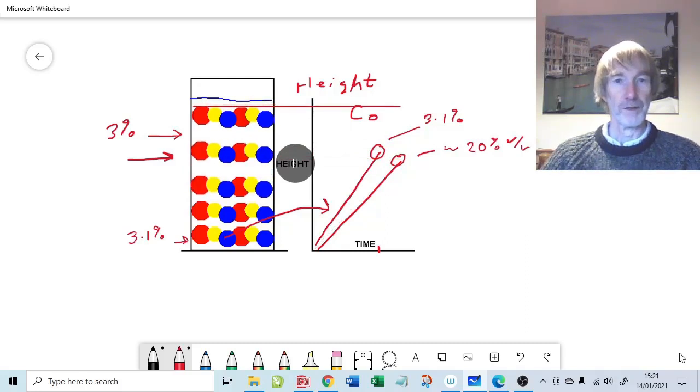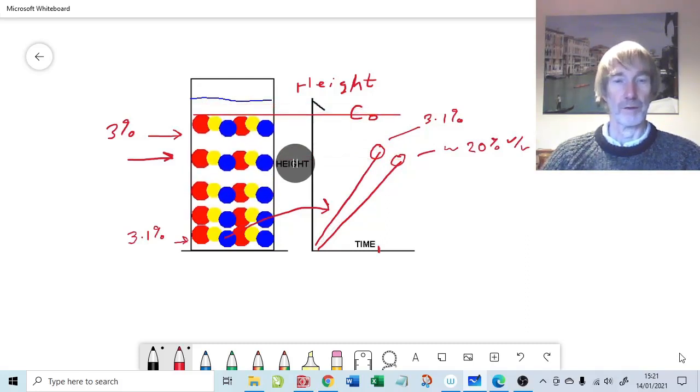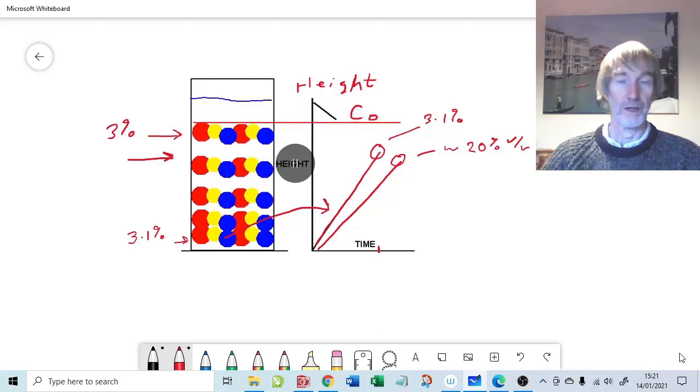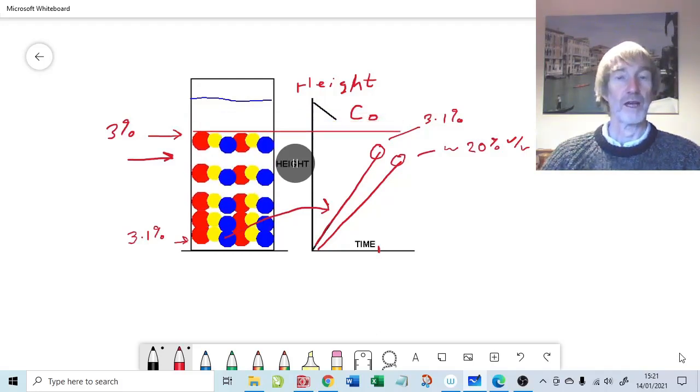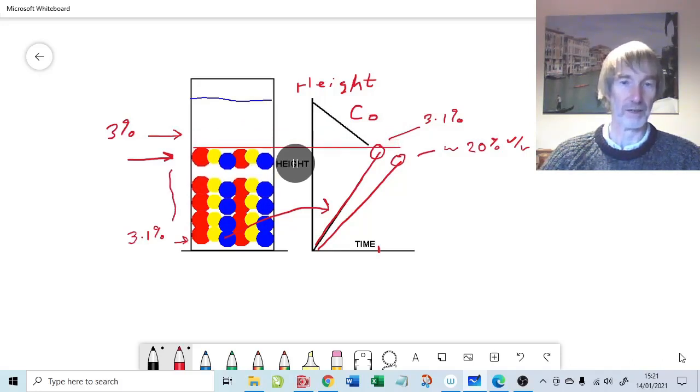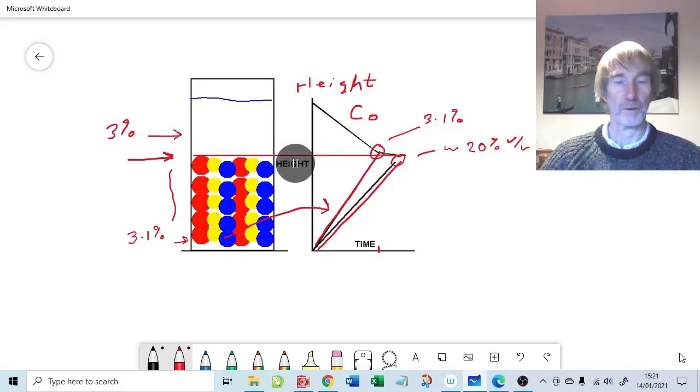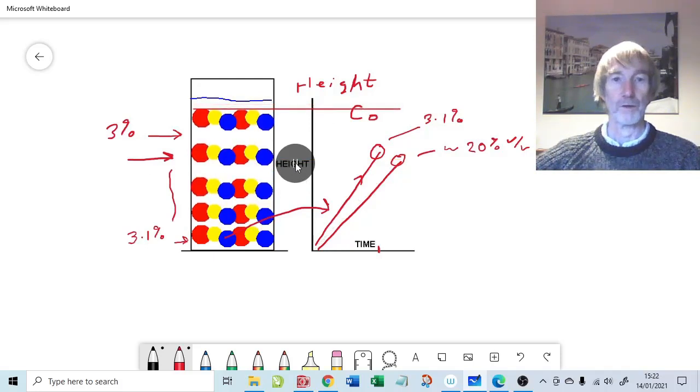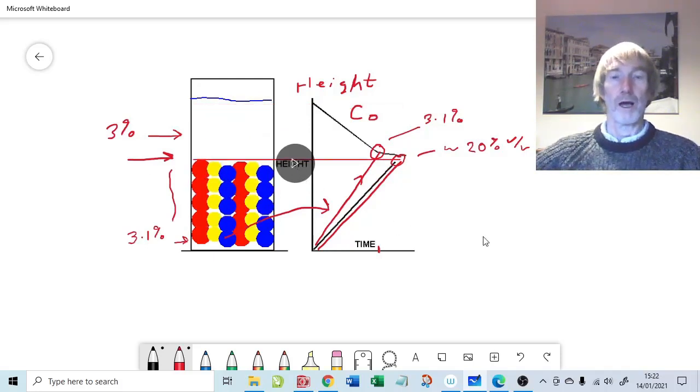So that's essentially what the batch sedimentation looks like, with this constant rate to start with, and these characteristics which you clearly can't see because it's all just a mess under here. You can't actually see these characteristics, but the characteristics, if you were to just consider a fixed concentration, are doing this uniform increase in terms of height and time until they reach the interface just there. So that's what's happening. Okay, so let's just pause that a moment. Okay, so that's what's happening in batch sedimentation.